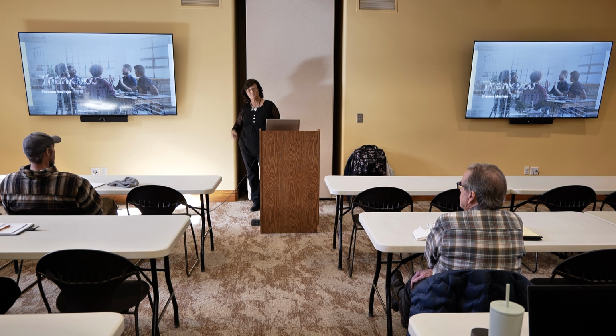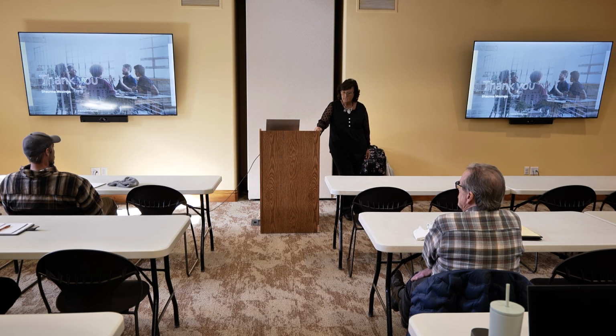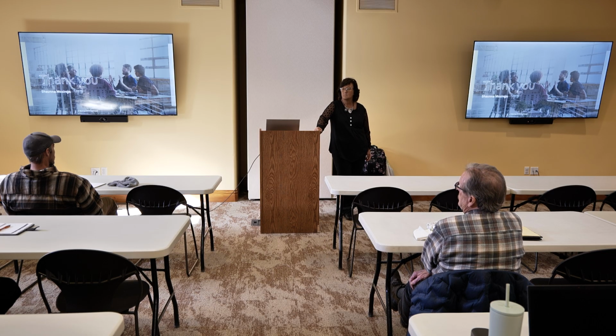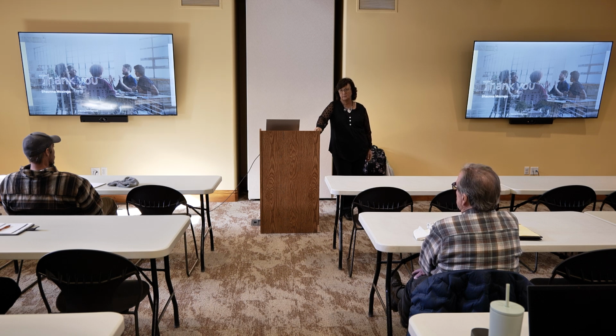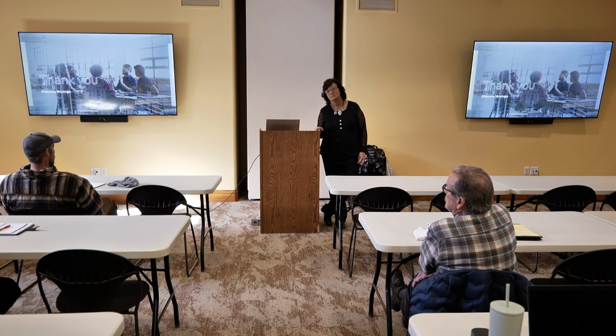So is there a provision in the code, like when you use the calculator on continuousinsulation.org, it's factoring in the siding you're using, every wall, and you can factor in degree days instead of climate zone. And you can make an R6 pass, but the code says R7.5. So is there prescriptively? Right. But so you can look at the whole assembly and solve that problem.